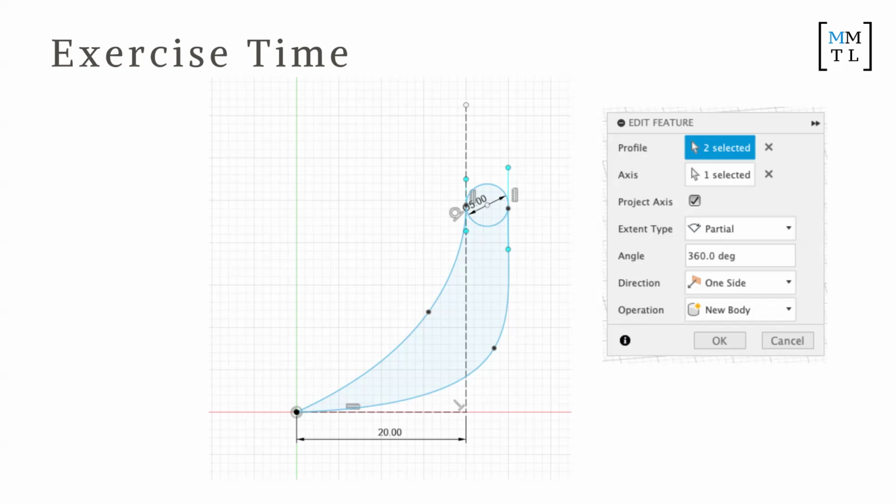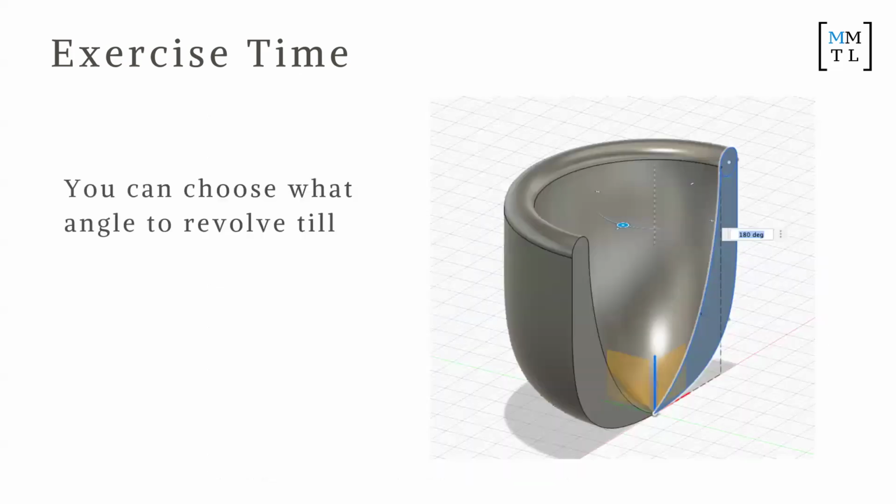I put it so it touches, not tangent, the circle, so it touches the circle. Yeah, and then you'll tangent it in a second. Put it on the edge of the circle. It's just like that spline. Beneath this line, and then do another line. Same thing, just on the other edge, actually.